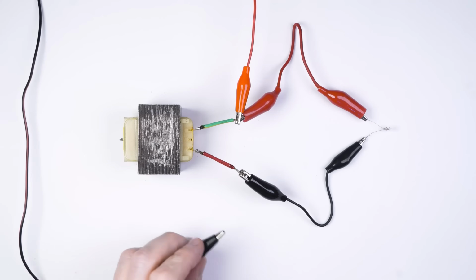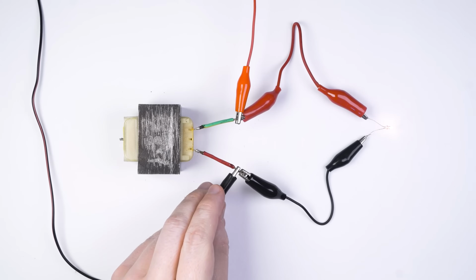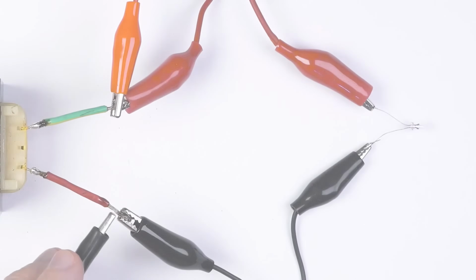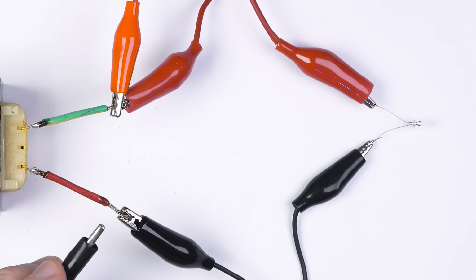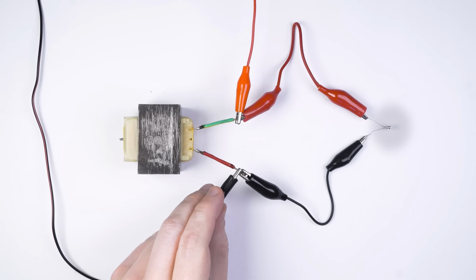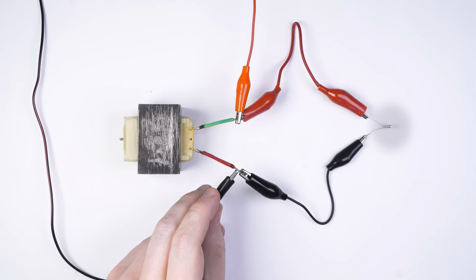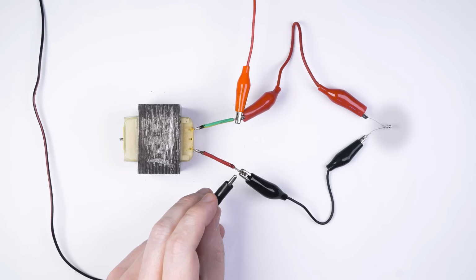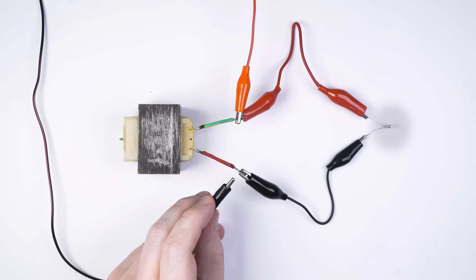Now let us wire the bulb and the choke in parallel. The bulb also turns on with a slight delay, but that is because the very first moment the choke imposes load on the battery. A more interesting effect is observed when the battery is disconnected. We can see that the bulb does not go out instantly, but gives an additional flash. This happens because once the supply voltage is removed, the inductor transfers the energy stored in its core to the bulb.